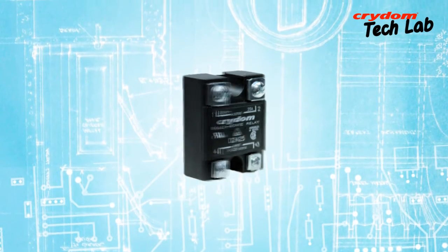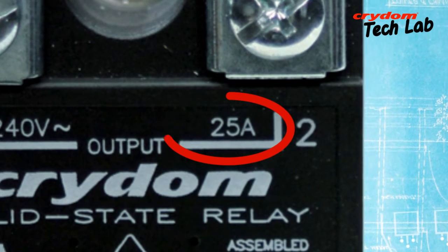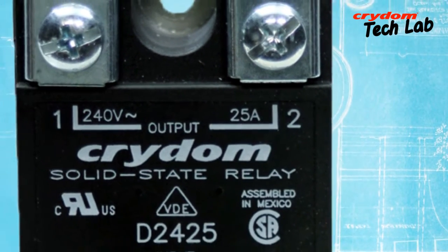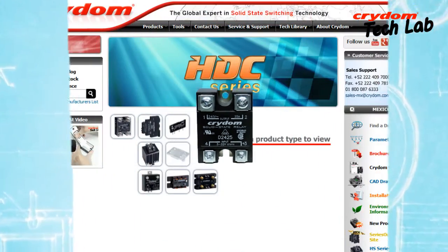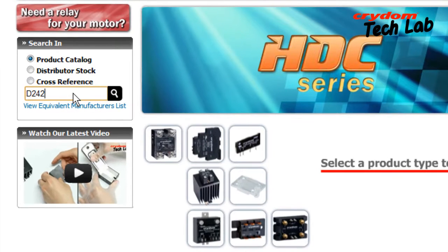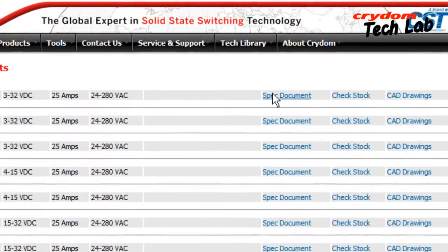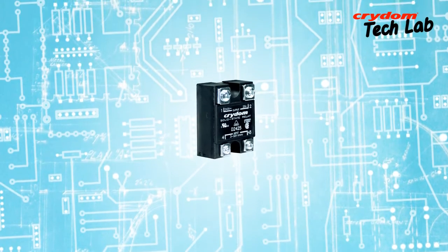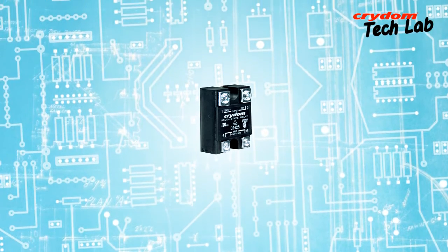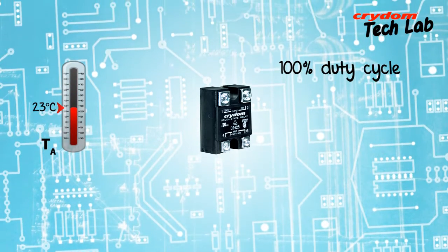Note that the load current rating of the SSR or SSC is always marked on the relay, but owing to the limited printing area available on most SSRs and SSCs, complete ratings and conditions may not be fully described on the relay itself. To ensure the proper selection and use of SSRs or SSCs, product specification sheets accompanying the relay or available on the manufacturer's website should be reviewed carefully to ensure a full understanding of the relay's ratings and associated conditions. Most panel-mounted SSRs or SSCs' maximum output current ratings are based upon 100% duty in a given ambient temperature when mounted on a particular size heatsink.